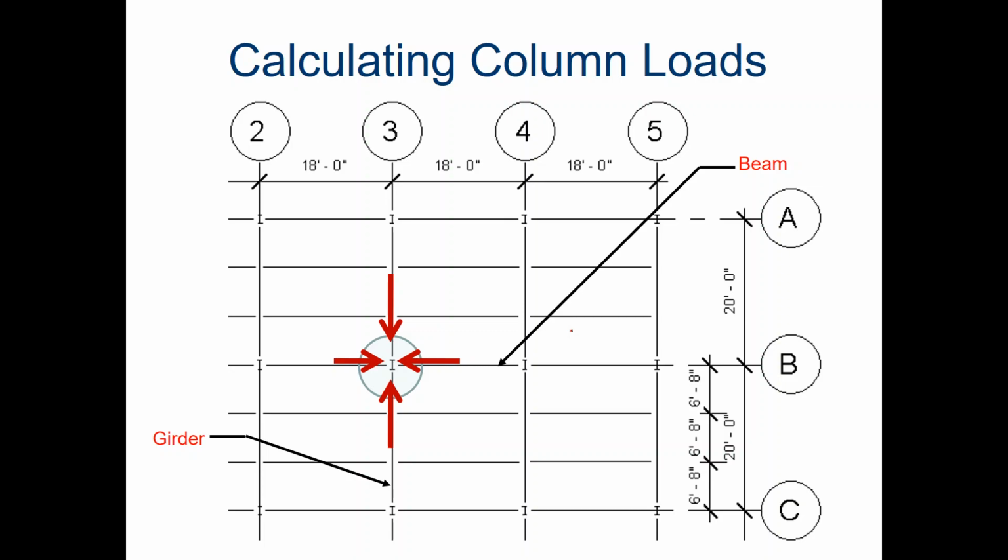And now for these interior columns, the tributary width for columns is just going to be from the column that you're trying to figure out the tributary width, or the tributary area, halfway to the next one. So if we have a column here and a column here, it would be a line kind of along there, a line going down there, over, and sort of up there. That there would be the tributary area of that column.